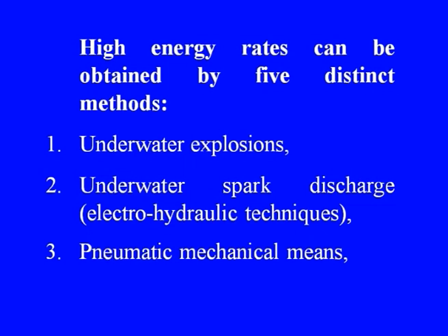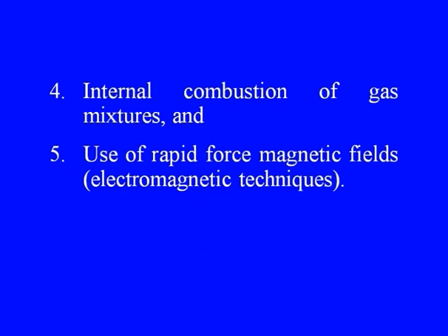So, these are: number 1, underwater explosions; number 2, underwater spark discharge, which is also called electrohydraulic technique; number 3, pneumatic mechanical means; number 4, internal combustion of gas mixtures; and number 5, use of rapid force magnetic fields, which is also called electromagnetic technique. Let us first of all discuss the underwater explosion technique.